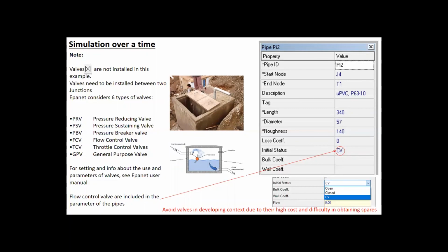The water is coming in and just destroys all the energy through this, let's say, chamber, and then you really can decrease a lot of pressure on the pipes. And another valve that is always there in the system is the control valve in the pipes. When you have it open, it means the water in the pipe can run in both directions.